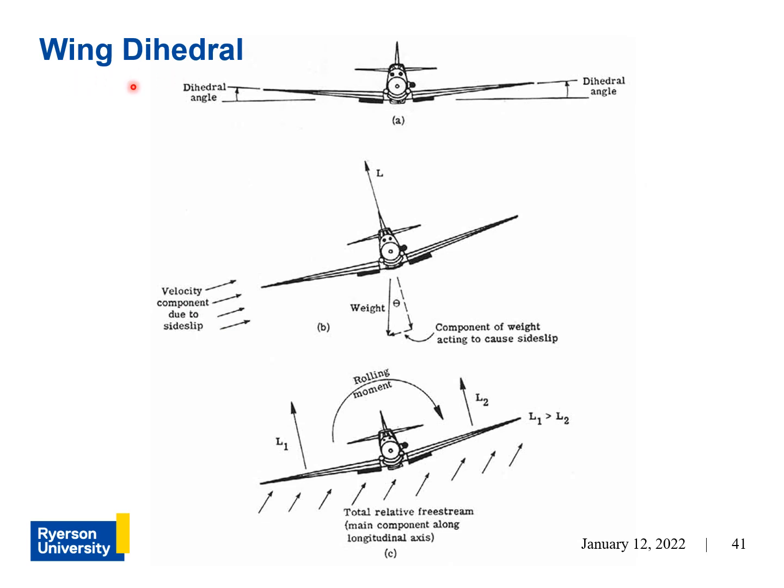Now here's another important concept, and it's called wing dihedral. Wing dihedral is just the angle of the wing with respect to the horizontal when seen from the front, as you can see here. A positive dihedral means just the tips are higher with respect to the horizontal here. And what that does is that it tends to roll the aircraft back to level flight.